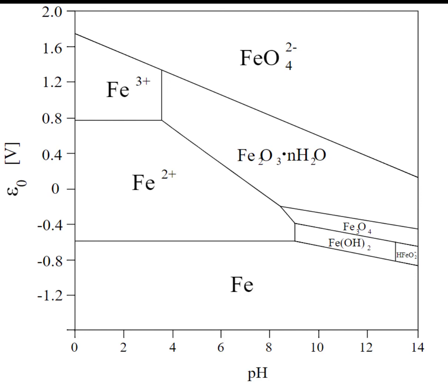Remembering that this Pourbaix diagram is a thermodynamics diagram, so it will tell us what would happen after infinite time, and we're misusing it to tell us about what will happen over shorter periods, because we've got an equilibrium that is not constant, it's not a thermodynamic equilibrium.